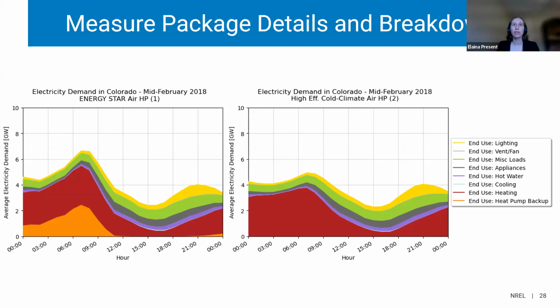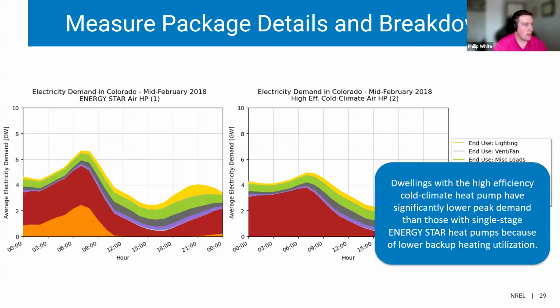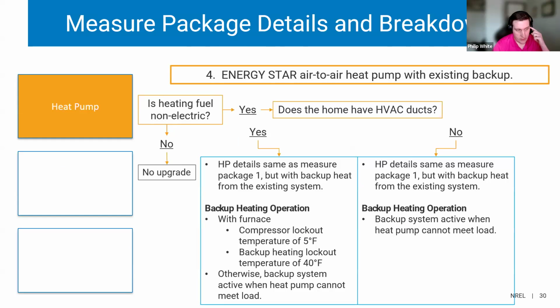Next question, how are the changeover temperatures determined for all measure package heat pumps with the various backup sources? Yeah, good question. Well, if you remember from 2022.1, we had a switch off temperature of like 40 degrees, and we asked experts in the field, especially internally at NREL, what would be something more sophisticated, more representative of what's happening in the field with these lockout temperatures.